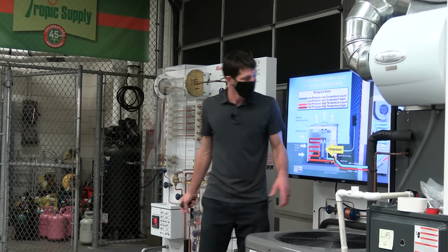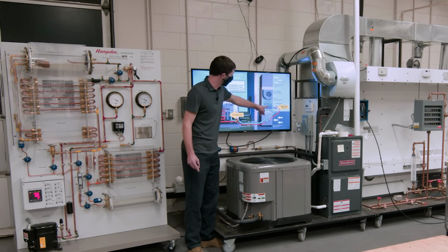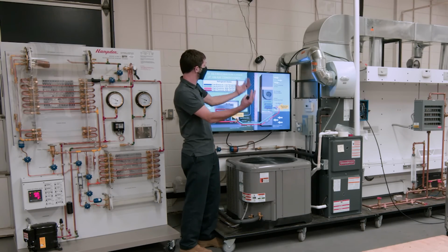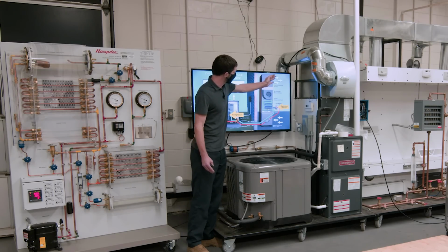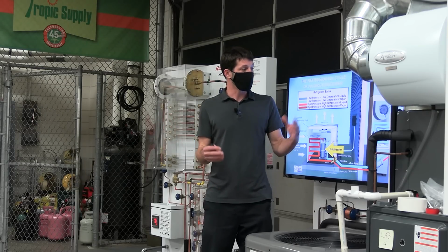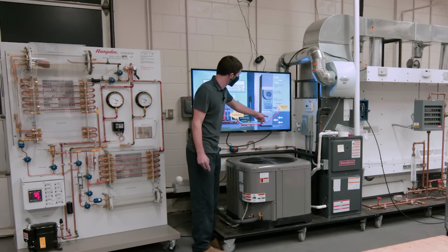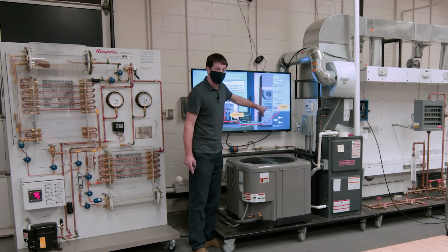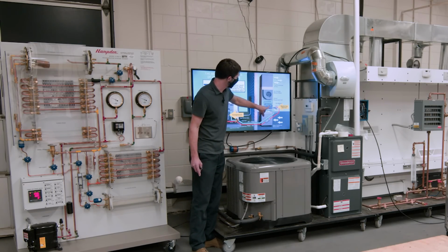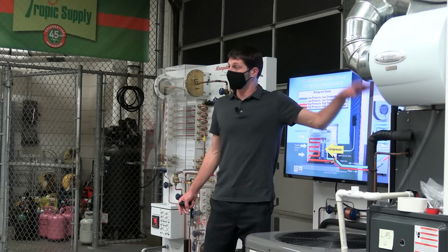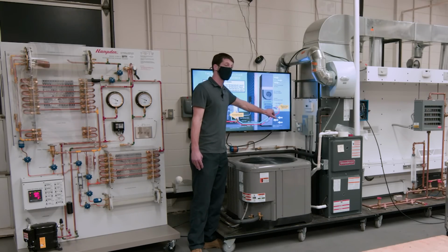An efficient superheat, which is, so say this is 40 degrees all through here, and you have 70-degree air passing across this, and in this case we have a thermostatic expansion valve, so say we have 20 degrees across here, you're going to have 50-degree air coming out, and of course that's based on also an average humidity. If you have a high humidity, you may be lower than regular 18 to 20 degree delta T across the evaporator coil. But what's going to happen is this 40 degrees is going to stop even maybe right here. And then you're just going to have the vapor temperature. So if it's 40 degrees and then it starts rising, it's going to come out here. It could even come out the same temperature as the air coming across that coil. It could even come out as like, say, 69 or even 70 degrees.